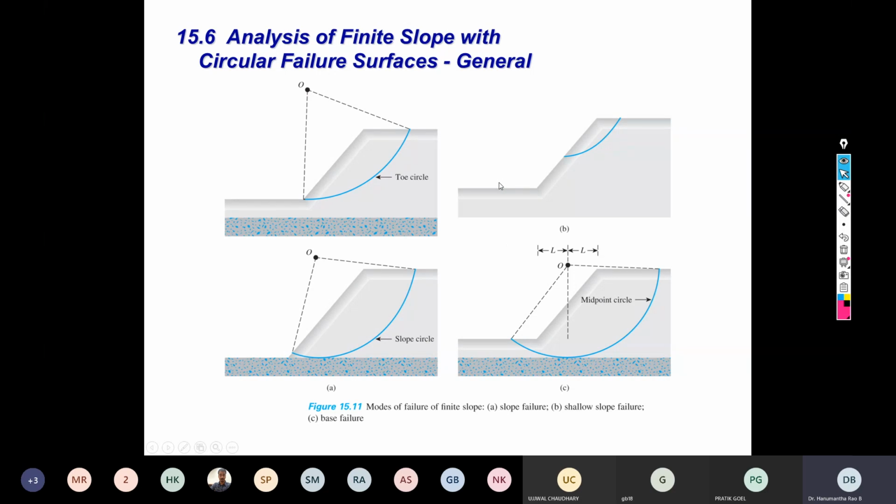The failure confined within the face predominantly happens when there is a contrast in the density of the material. That means when the compaction is inappropriate, where the upper soil is compacted high and the lower soil is low, or vice versa, then one can see this kind of slope failure.